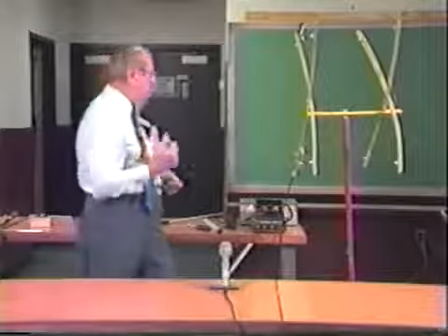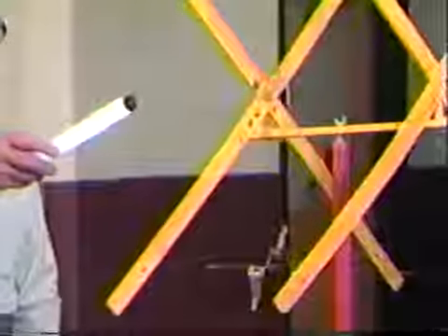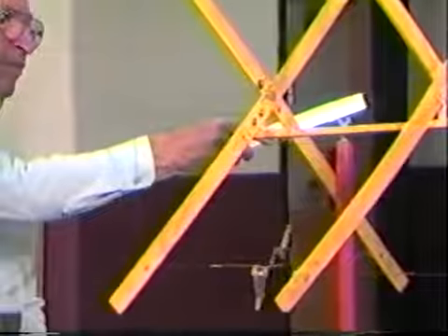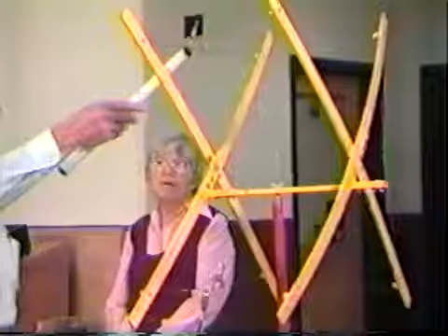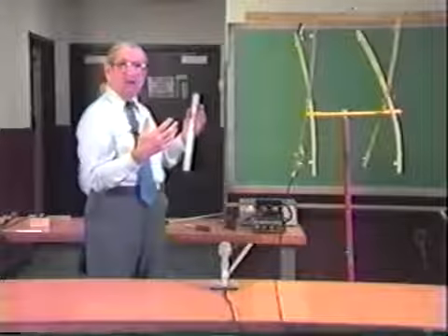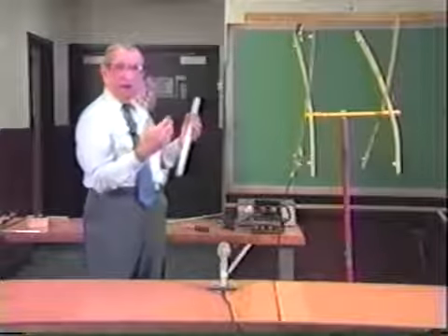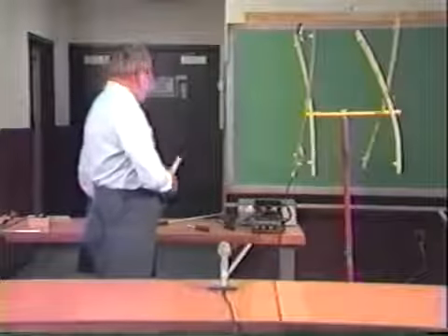I want you to notice that the antenna has a voltage loop on the side, okay? And of course, there'd be no voltage loop here. That's the current loop. And it's the same situation that we had before when we demonstrated the standing waves on the dipole or on the yagi or whatever. So that's a very effective antenna.